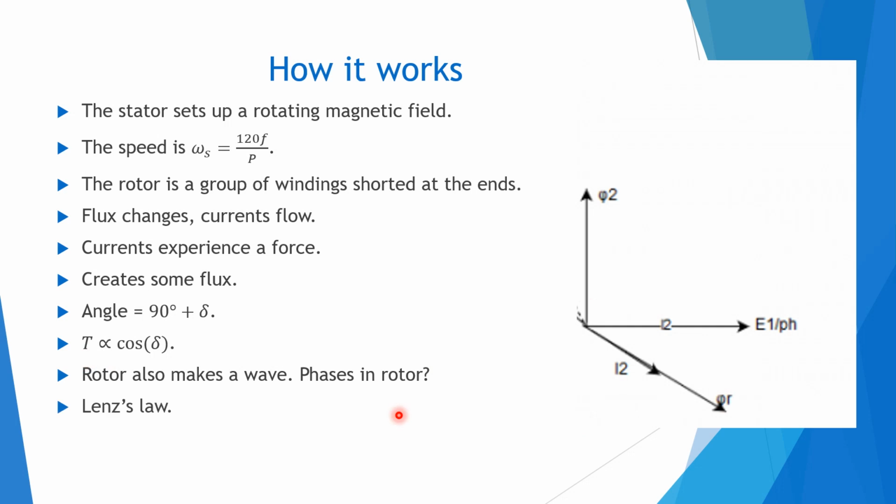Now notice that I've been drawing these at some angle, right? But if you thought of the rotor as being completely resistive in nature, then this phase would come along here, and had it been completely inductive in nature, that flux would have come here, according to what we have been talking. And the flux coming here makes sense. Why? Because that is what Lenz's law says, right? If you have some flux and that is changing with time, what your phasor would like to do is try to negate it. It would try to pull it down. So yes, the directions do make sense.